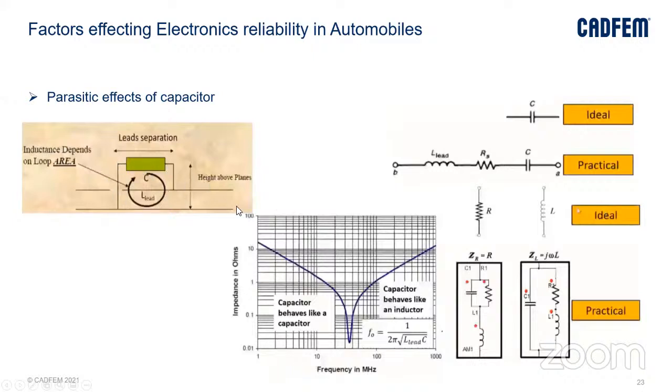This difference in lengths could give rise to a different kind of impedance value, which behaves like a capacitor at certain frequencies and like an inductor at certain other frequencies. So the user needs to take care while dealing with such designs. This is not only with the capacitor but with every lumped component, like R, L, and C as well.